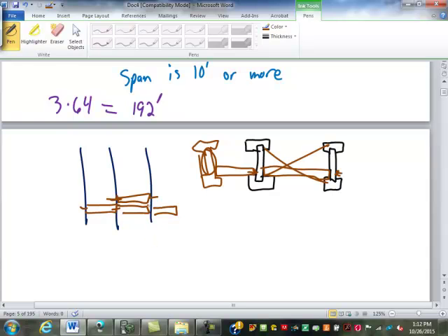In a lot of cases, if you're going to sheetrock a basement ceiling, that qualifies as your strong back bracing. I would not do that. Code, I believe, in most cases allows you to just sheetrock the ceiling and not brace. I don't like that.